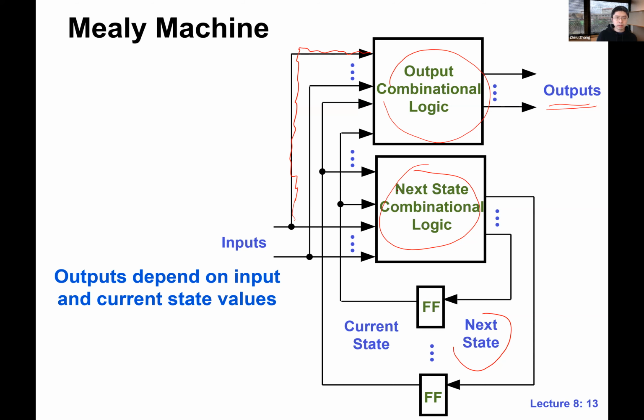But going forward, when you design your actual circuits, you're going to design FSMs and microprocessors. So we are not going to be dealing with latches. That's why I mentioned inferred latch. When you see the warning inferred latch, that's bad news. Get rid of that warning.